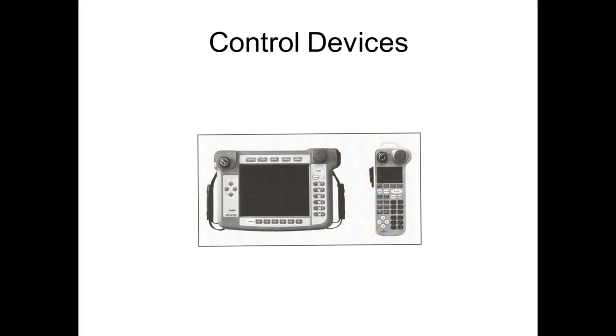We have different ways robots are programmed. We'll talk about continuous path and point to point. All these robots right here are what we call point to point robots. So what we do on these robots is we program points, which is probably 90% of the programming out there. And depending on the type of move, it would determine how it moves between those points. So I would take the robot, move it to where I wanted to go, and say, okay, remember this point. When I say remember that point, I also say how I want to move from the previous point it was at. That makes sense. We call those point-to-point robots, and these are probably 90% of robots out there.